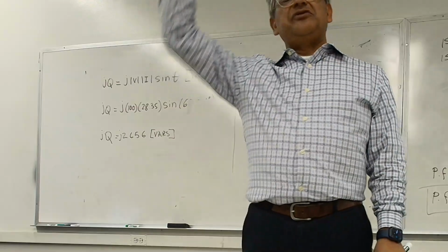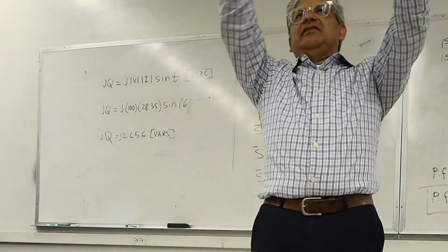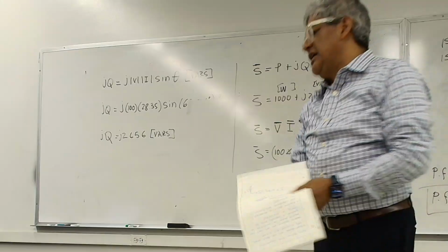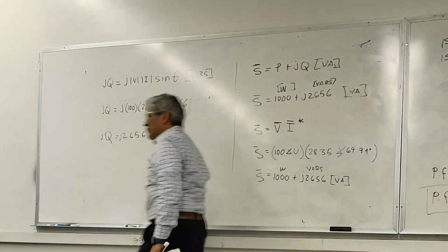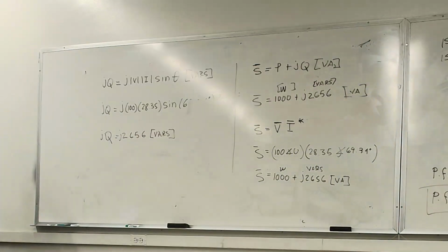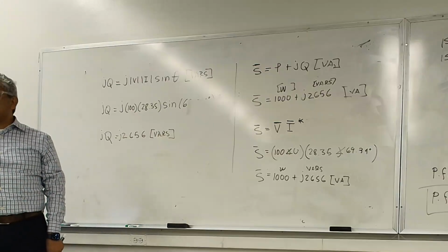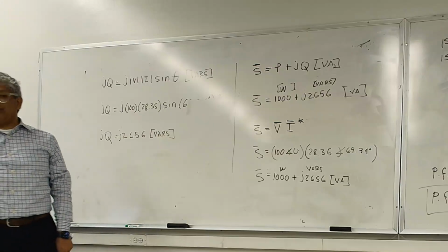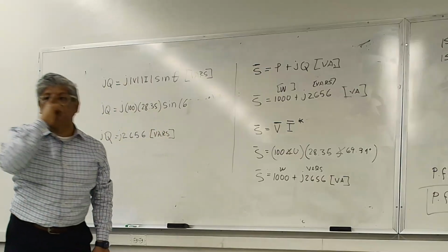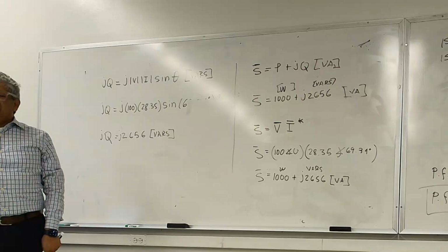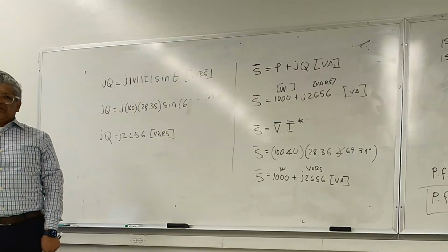Distribution capacitors, and you see this on the pole. You see these cans, they look like boxes on the poles. That's a capacitor bank. And the capacitor banks on the distribution circuits do two things. One, they improve the power factor. Basically, what they're trying to do is get vars closer to the customer, right? Number two, they improve voltage. Capacitors have the ability to raise the voltage.